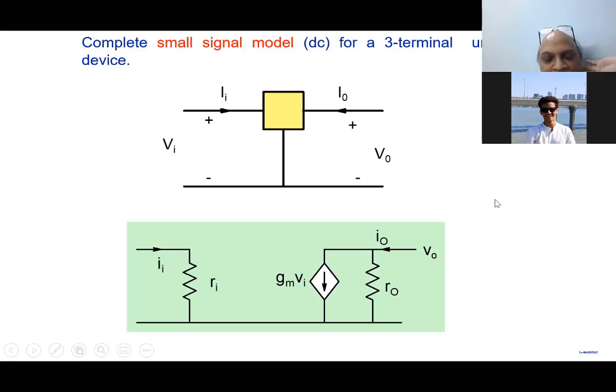And the reason why this is important for us, the time before us is limited in terms of what we can do with transistor amplifiers. But what happens is the transistor is a nonlinear element. And normally what we do is we apply some DC voltages and currents to our transistor so that it operates in a suitable region of its characteristics. So the purpose of DC voltages and currents is only to push the transistor into an appropriate region, such that it may be capable of amplification. Then we apply a small signal that we need to be amplified by the transistor.